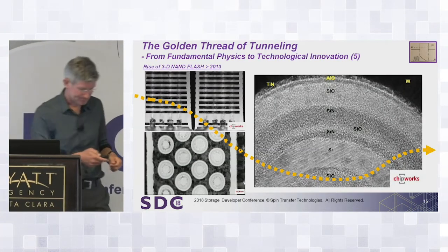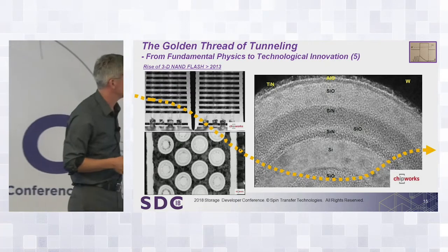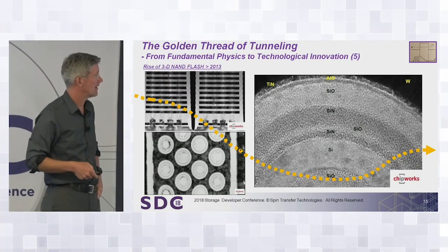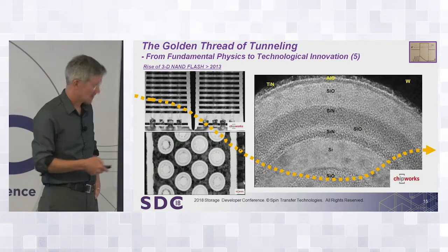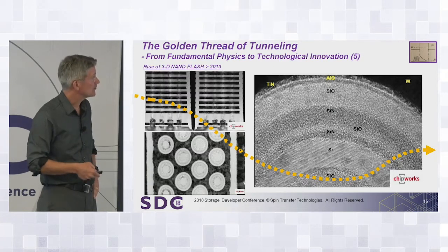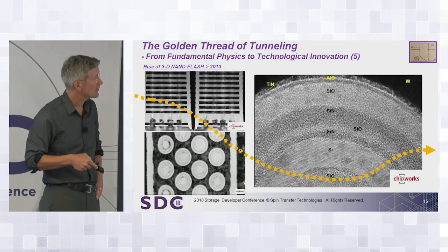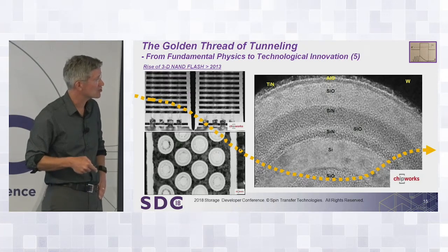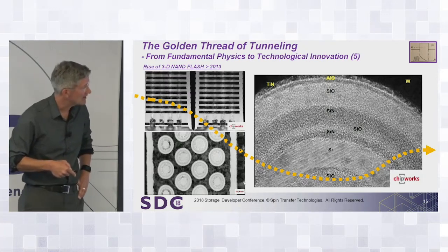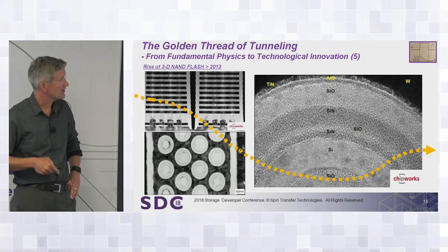And there it is. So this was, again, from ChipWorks, Tech Insights. Dick James sent me these, and you can see the structure here. But again, look how complicated it looks. But it's not. It's the field effect device in a ring. But here's the gate. Here's the reservoir of charge storage. Here's the channel. Here's the field effect device. Here's the tunnel dielectrics, and so on.